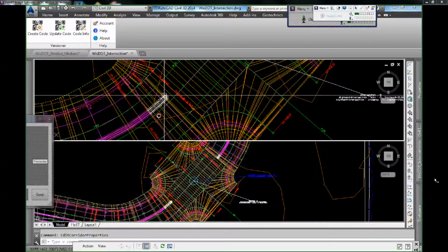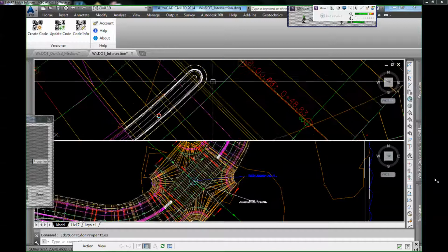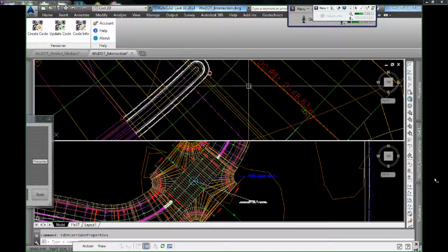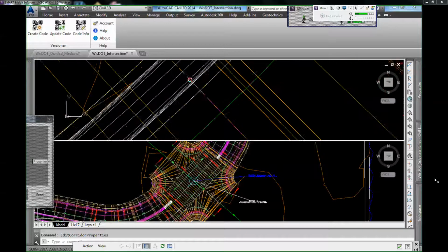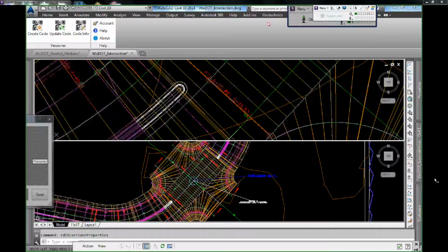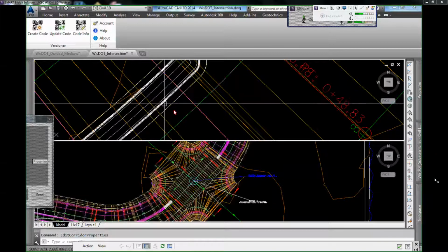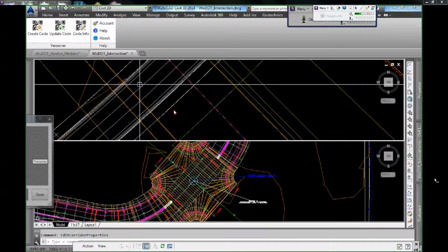Now, the bullnose that you see here, all this is a bunch of feature lines. This outer feature line is draped on top of the top surface of the corridor, okay? These other feature lines are just using the stepped offset command, okay? I've got access here to some third-party stuff. You probably can't see it, but I can't because I've got my little menu bar on top of this. But I've got a little third-party app here that I pick on this outside, and bam, it automatically builds all these for me. So this takes me about 2 seconds to create, okay?